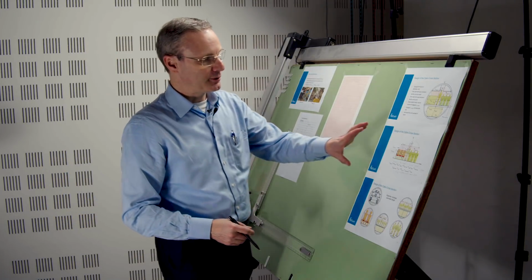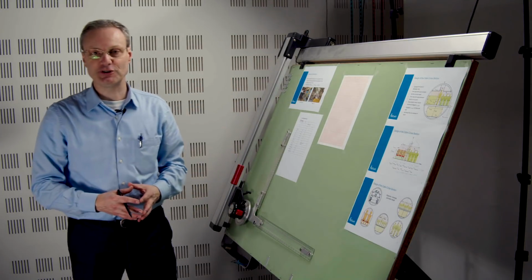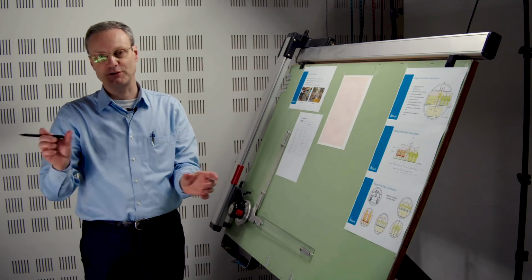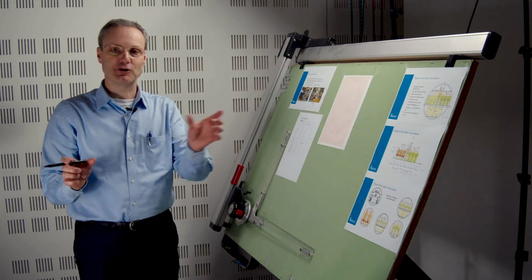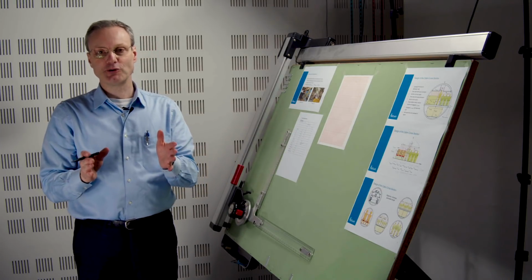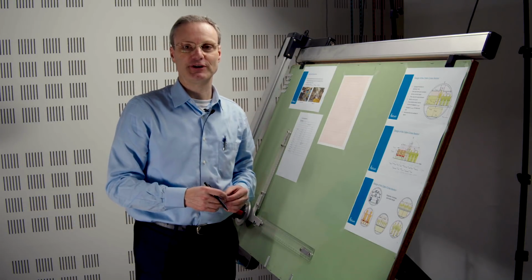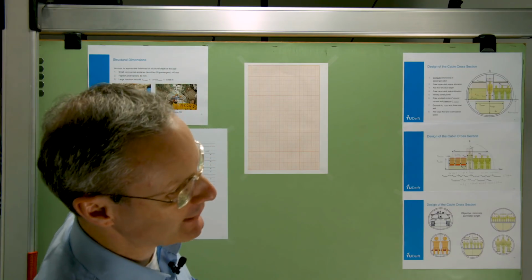And since we don't know where the center line is going to be, because we have an odd number of seats, we cannot split them 2 on the left hand side, 2 on the right hand side. That's 4 abreast, or 3, 3. We have 5 seats abreast, so it's going to be a 3 plus 2 split. So the aisle will not be in the center line. So that means we will not be able to draw the vertical center line of the fuselage yet. We will do that later on.